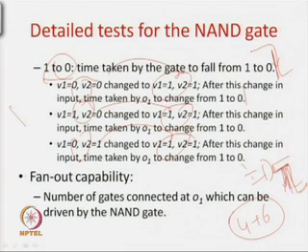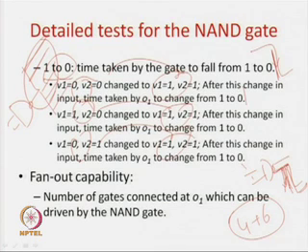Now, another important thing which you sometimes take into picture is your NAND gate's fan out. I think you might have seen the fan out case in our previous modules: this NAND gate can drive, or needs to drive, several other gates. The question is what the drive capability, or fan out capability, of this NAND gate is. I am not going into details of how the test can be done, because it requires some complexity, but you have to tell that these gates can drive so many other gates with so much load in so much time. So, this is about the fan out capability test.